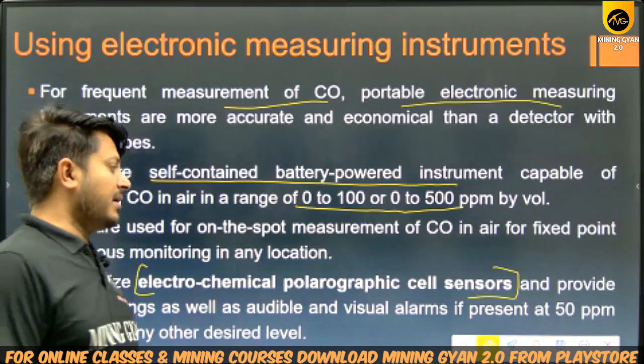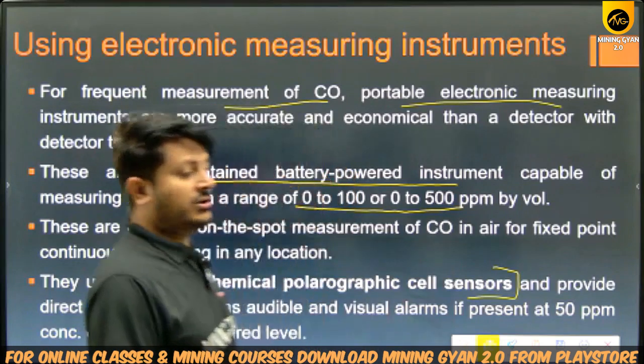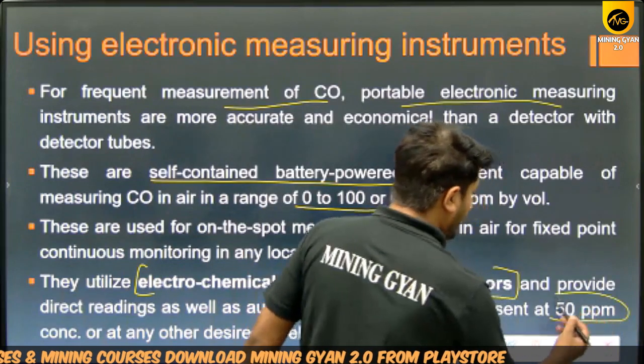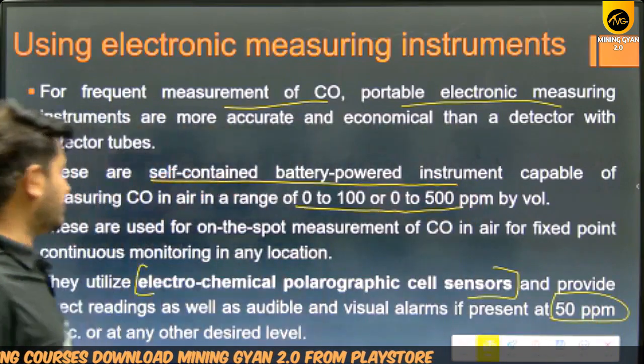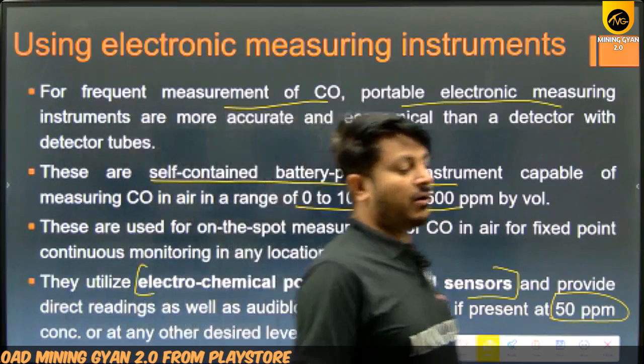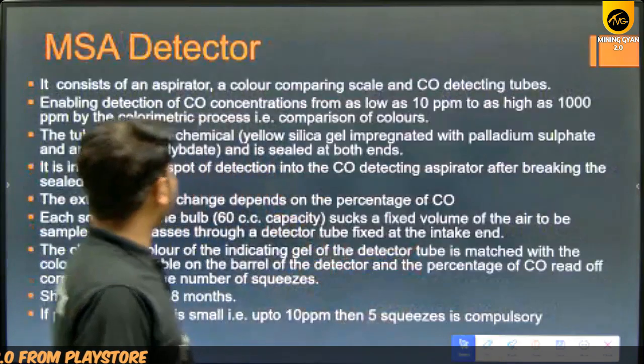It provides the readings with an audio-visual alarm: if 50 ppm or more carbon monoxide is present in the atmosphere, then in that case it will provide you the audio-visual alarm, like a warning alarm.